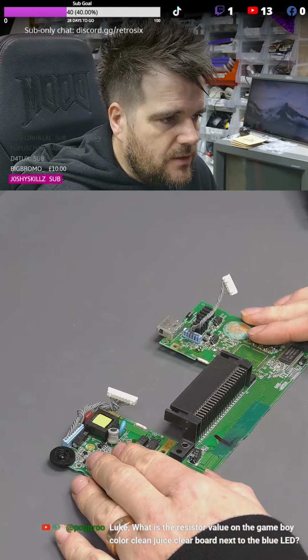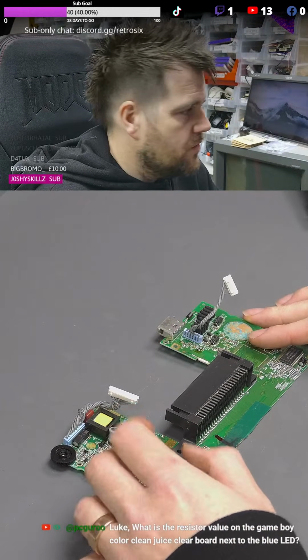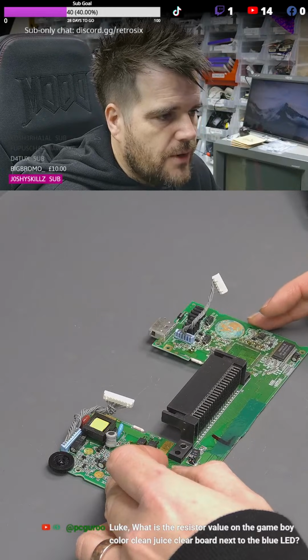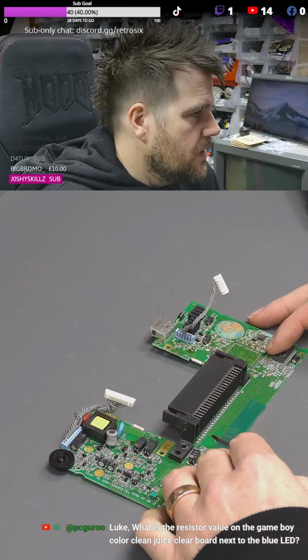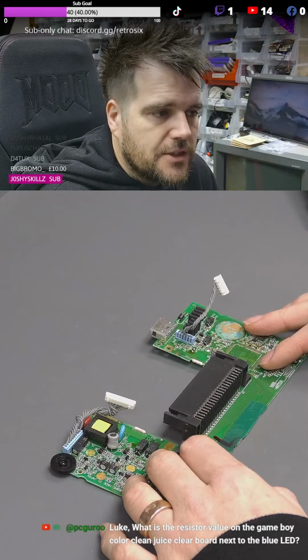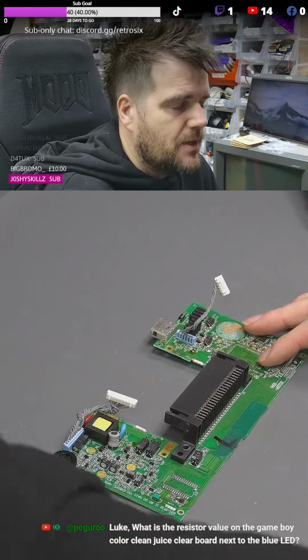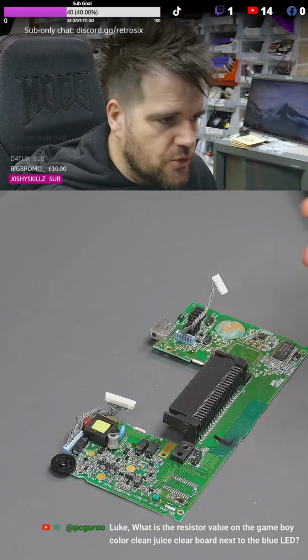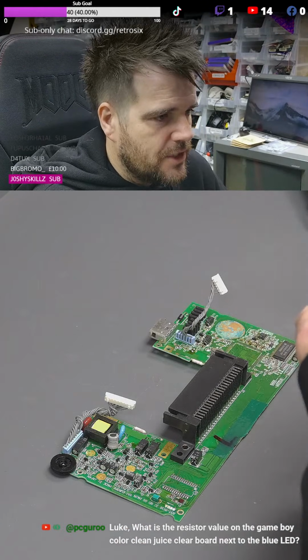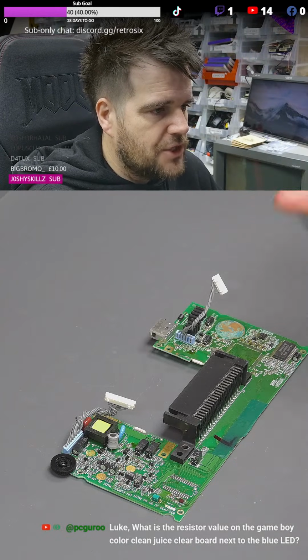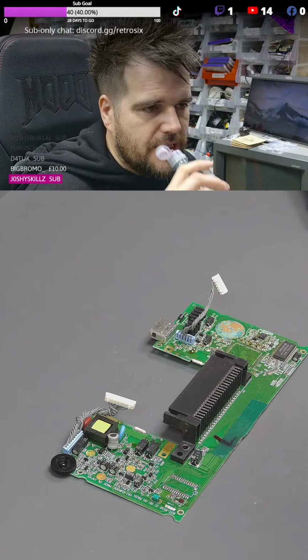If they fully fail, or sometimes bridge, or there's other issues, it's called a dead short. So a dead short is basically an almost 0 ohm resistance short. So they're the two major kinds of shorts. Some people, especially me as well, will probably say the same thing. I might just say, oh, there's a dead short on the board, and it's not a dead short. It's actually a 50 ohm short. But take it with a pinch of salt when people say a dead short or a short. They are technically two different things.